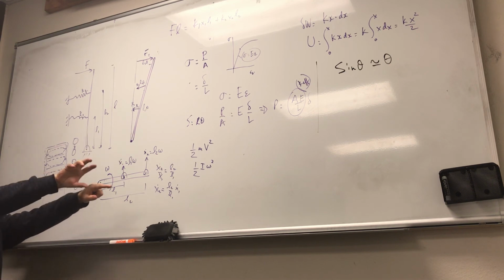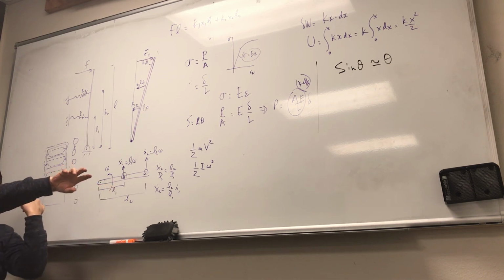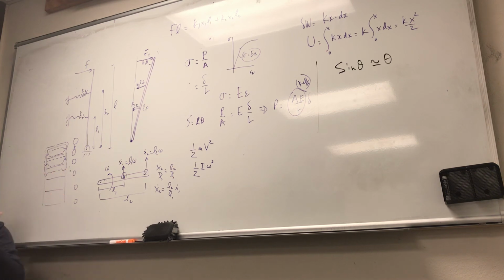As my mass tries to go to the right, my friction force changes sign and goes to the left. And in each one, there is work that is being done, which is equal to mu k times N, the normal force, times the displacement. So each time some work is being extracted from the entire energy of the system, and eventually the system is damped to nothing. And then there is also what we call material or solid hysteresis damping, okay?